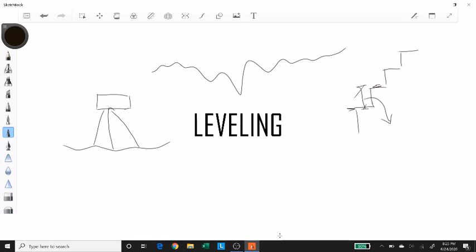But what you get from the instrument is that it has a telescope attached to it, and when you look through the telescope, it magnifies your vision, and the vision that you get out of it is something like this: a telescopic vision with crosshairs in the center. And what you are trying to view is a bigger version of a foot scale that is called a leveling staff.